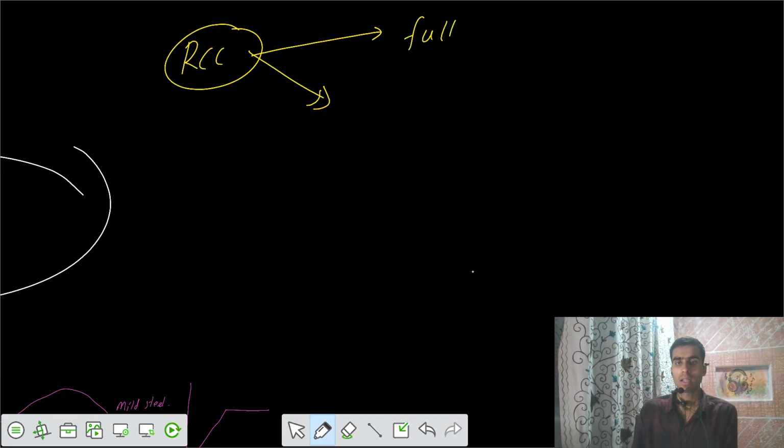Steel is the costliest material, and we want to utilize it effectively. For that, we have to develop stresses in the steel up to the yield stress or more, and ensure that yielding of the steel happens. For steel to reach the yield stress, there should be some strain associated up to that limit.